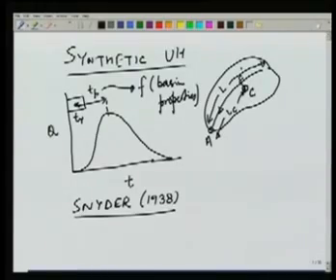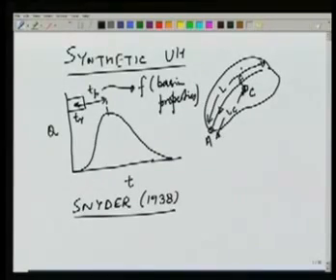So using these two parameters, L denotes the size of the basin because larger L value means a larger size of basin, and LC represents the shape of the basin. So if the basin is wider near the point A, LC would be smaller. If the basin is wider away from point A, then LC would be larger.